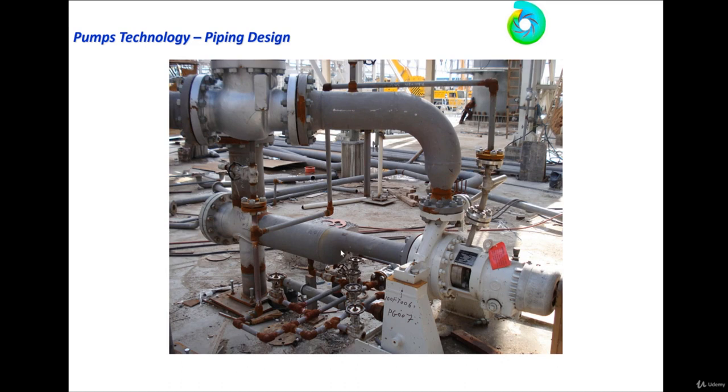This is another practical point from the piping side. The piping engineer has to consider that usually the pump suction and discharge nozzles have different sizes than the suction and discharge headers. So how do you connect the suction? You have to connect the suction nozzle with the suction piping using an eccentric reducer, flat on top. This shape gives the most uniform flow.